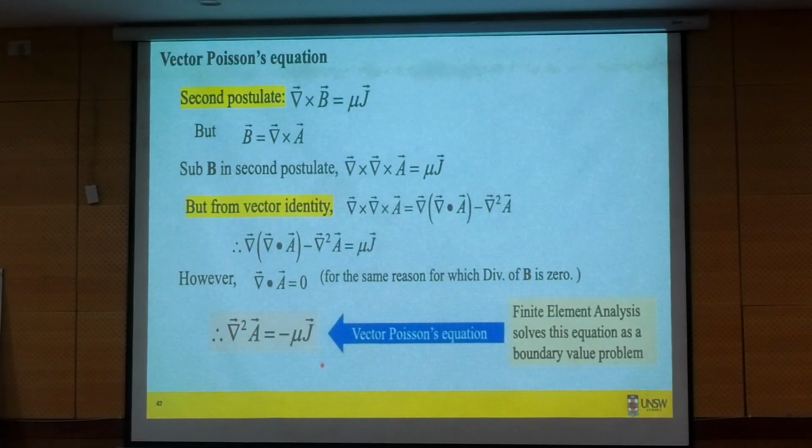In fact, all the finite element analysis that we talk about tries to solve this equation at the back, which we don't see. Those who use finite elements only see the geometry and how they have solved the flux density, but in the back, it is trying to solve this equation. A could be a function of x, y, z, so it's a three-dimensional second-order differential equation, and you have to solve it using numerical methods such as finite element.